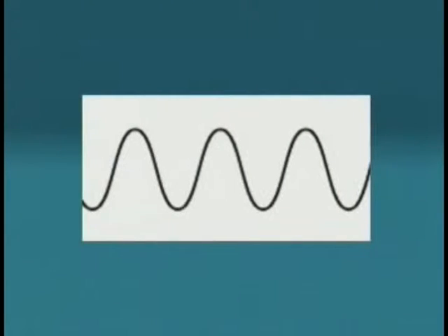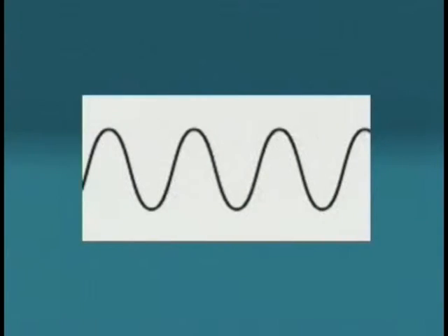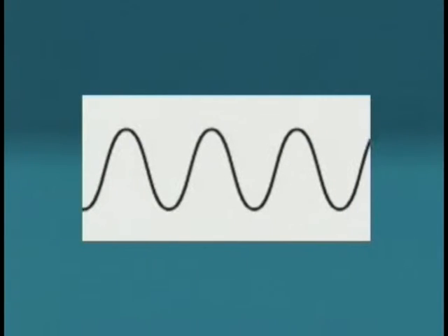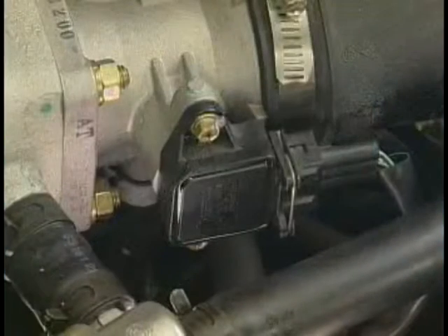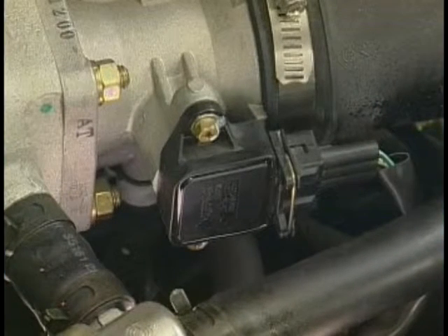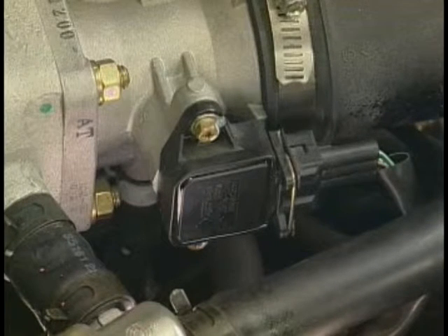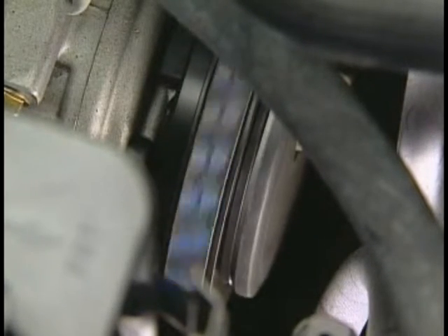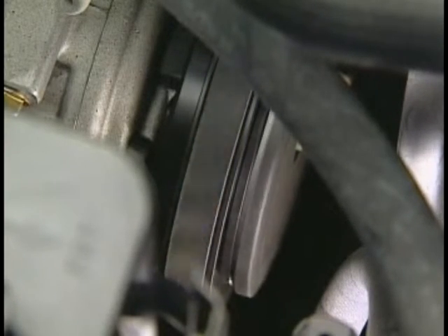As the vehicle speed increases, the signal increases in frequency. The vehicle's speed sensor is used by the ECM and BCM to determine airflow over the condenser and is a general indicator of engine operating conditions. The throttle position sensor is a variable resistor with a set of contacts for idle and a set of contacts for wide-open throttle. On electronically controlled engines, the air conditioning compressor is disengaged during high engine loads or when the vehicle is operated under wide-open throttle.